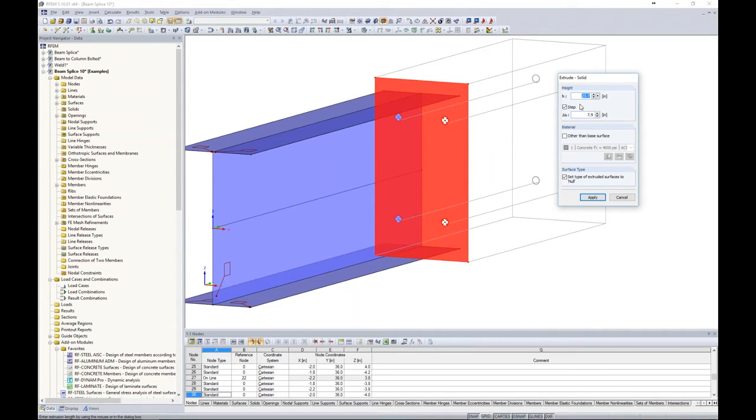Now this is important. If I have a 0.25 inch thick plate on the left-hand side and a 0.25 inch thick plate on the right-hand side, the height of my solid needs to be the sum of those 2 thicknesses. So in our case, this would be 0.5. Now in turn, if you had a 1/4 inch thick plate and a 1/2 inch thick plate, then that would be 0.75. So you just want to add those 2 together to come up with the total height when we're looking at something like a contact solid.